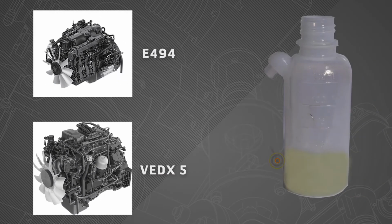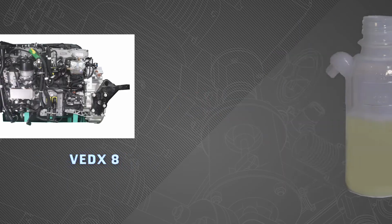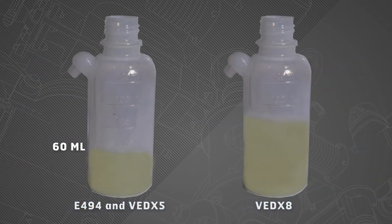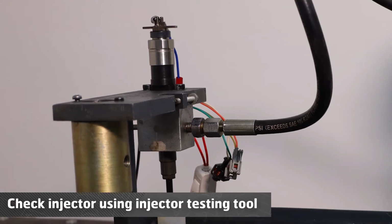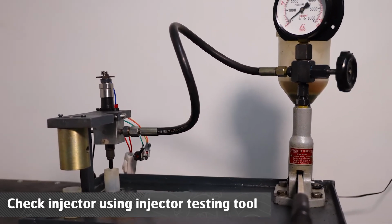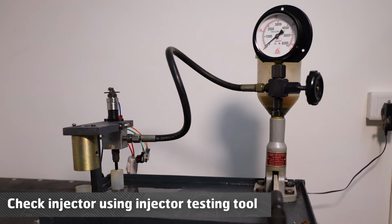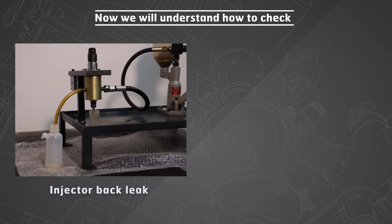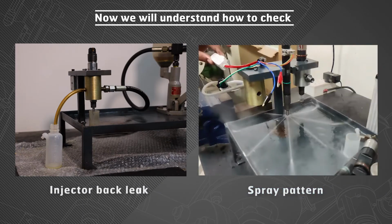The cumulative back leak should be less than 60 ml for 4-cylinder engine and 90 ml for 6-cylinder in 2 minutes engine idling RPM. If back leak is more than 60 ml or 90 ml for respective engines, then we need to check individual injectors one by one on injector testing tool and find out the faulty injector as per procedure explained.